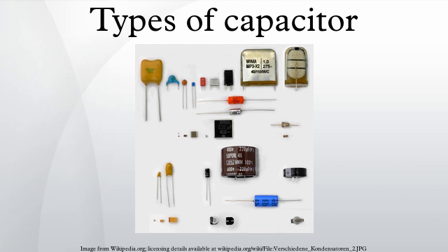In many cases the capacitor is used as a decoupling capacitor to filter or bypass undesired biased AC frequencies to the ground. Other applications use capacitors for capacitive coupling of AC signals. The dielectric is used only for blocking DC. For such applications the AC resistance is as important as the capacitance value.